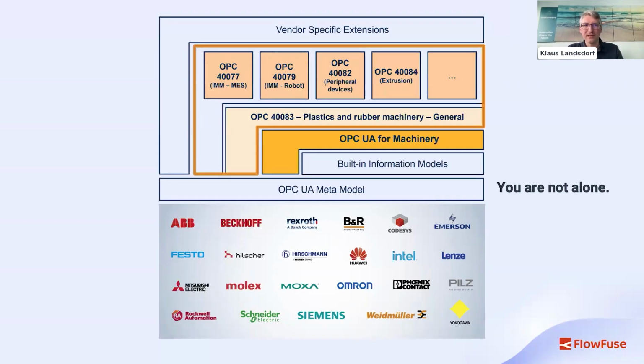At the end, OPC UA is absolutely ready, because you do not have a quality of service directly in the protocol. You can work with quality of service to manage how fast the protocol is handled in your network. But as I know, OPC UA really brings the message to the device, because you have all this auto reconnecting. That means if a client and the server are connected, they will reconnect every time if the connection gets broken, and all messages in between could be lost if you do not have historical access or something like this. But this is exactly what these mechanisms are for.